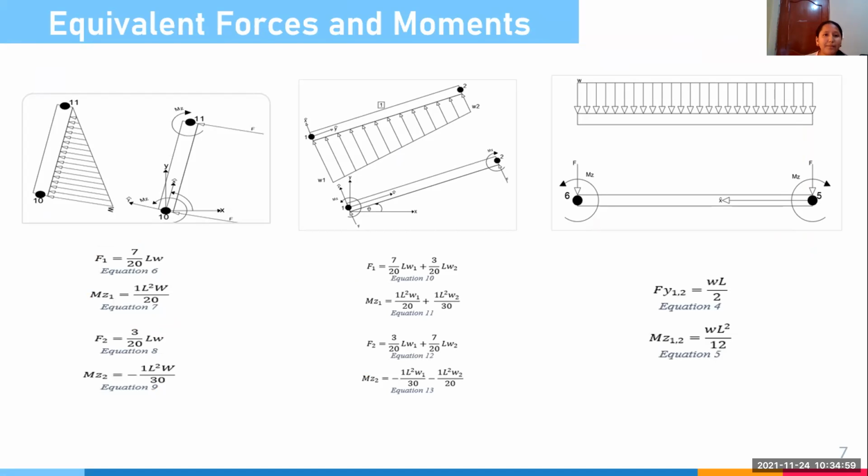Continue. Vessels in general are exposed to punctual forces, loads, and hydrostatic pressure. For this, we need to analyze what happens with the structure elements. In this case, we analyze the frame, which is exposed to different geometric loads, like triangular loads, rectangular loads, and the combination of both.